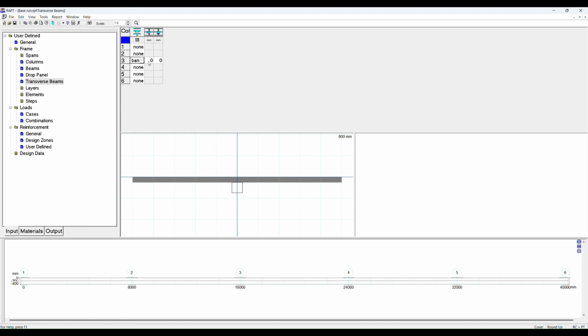Now a band, just like a drop panel, is included in the flexural calculations because the width of the band is large enough for shear lag not to discount the section properties in the calculations of strength, deflection, whereas if it was a beam, then the beam ends up becoming quite short and squat and becomes a part of the support, and then that ends up defining the critical section for shear calculations.